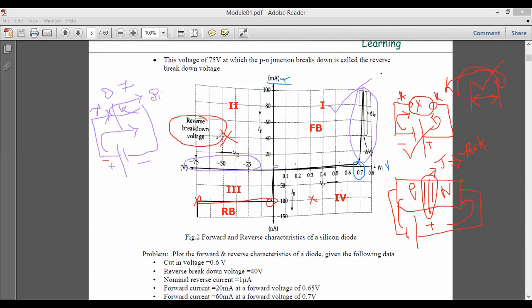So that particular voltage at which your small leakage current becomes very straight or sharp, we call it the reverse breakdown voltage. Now, when you have applied minus to P type and plus to N type, and you go on increasing, for example initially you have applied 5 volts and you are moving in increasing order, when you reach one particular point, that is called the reverse breakdown voltage.